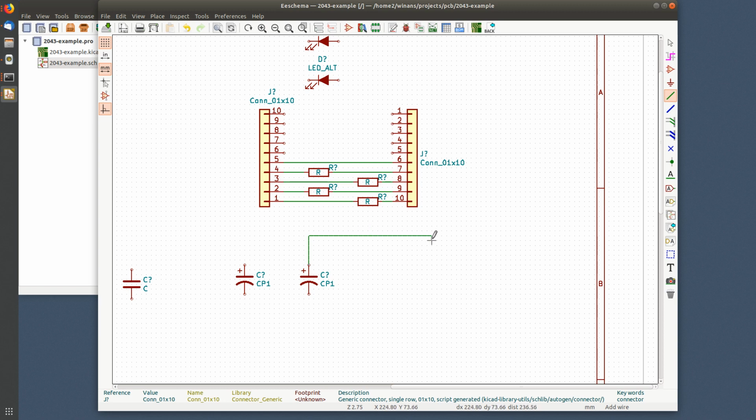All right, then you might want to come over here, and maybe you want to go up here, and then you want to come back. Well, it's trying to be helpful, but you don't want it to, so you're going to go like that and click it right there and say, don't go to the left yet. I want to go up and around and go to this LED like this, maybe. Okay, so I'll click on that terminal. That's how I draw that wire around there. Maybe I want to draw this one over to the left a little bit. I click right there, left mouse button, come down, and then I want to go to this terminal, but I don't want it to be that close. Maybe I want to come down over here. Click right there, left mouse again to connect the wire to the end.